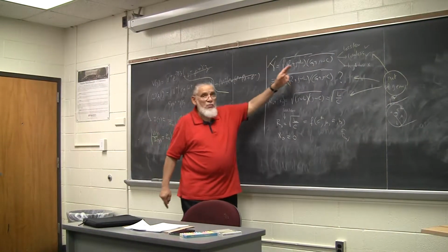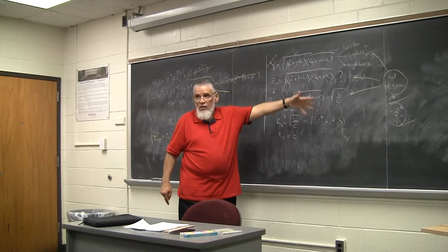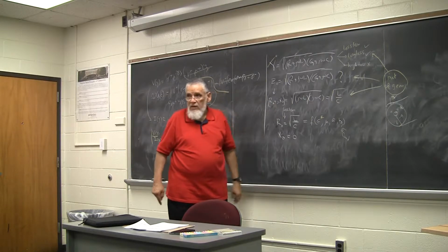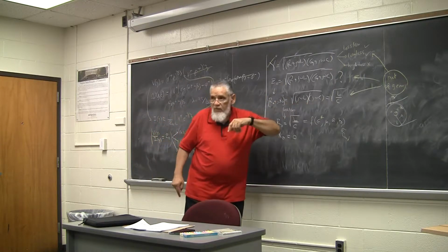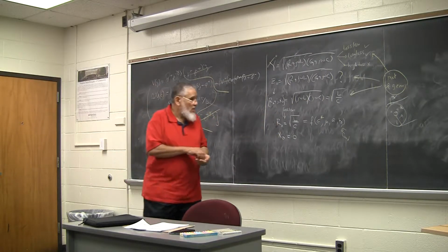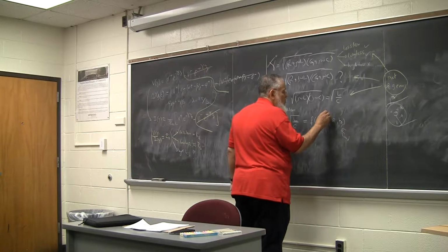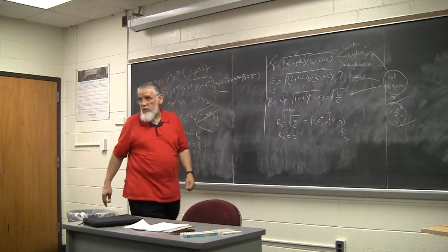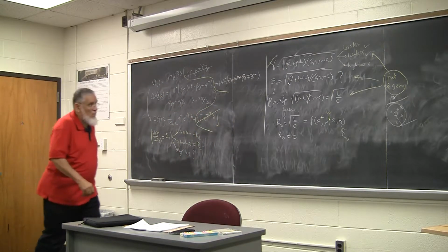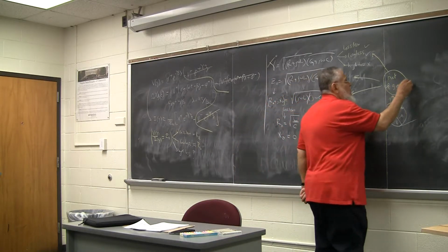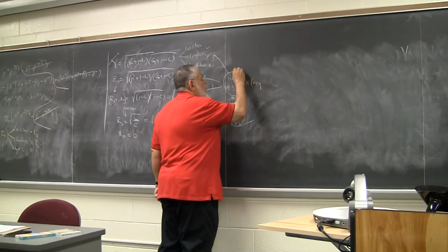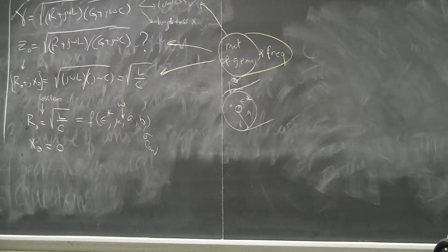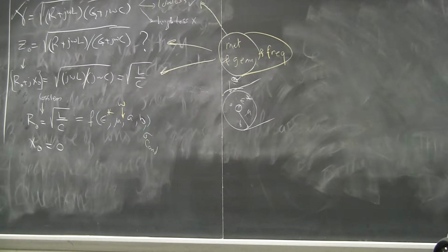So you can tell how much loss per unit length, how much phase constant, what's the phase velocity, and what's the characteristic impedance. Obviously, that is at a given frequency, right? I forgot to mention that. It's logical, but it has to be written as well. For completeness, omega also comes in the mix here, because that will change from one frequency to another. So, material, geometry, and frequency. For completeness, I should write that. If nonlinear, then signal amplitude will come in as well, right? But for linear, signal amplitude doesn't come.